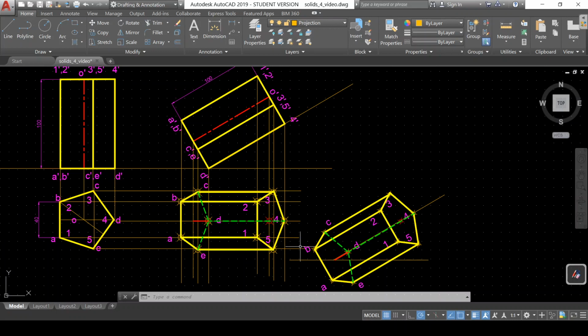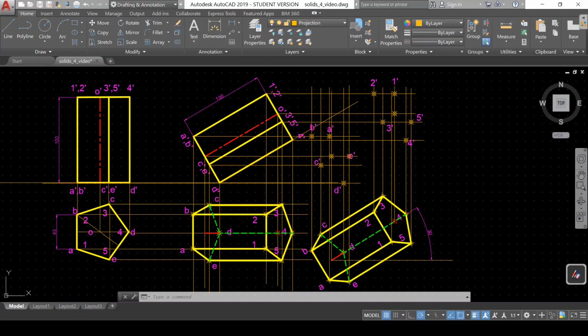In the second step, we have reoriented it. Now this axis view is making 30 degrees with XY or 30 degrees with VP. Now take the projections from this view, from the second step front view. The point of intersection should be named, and then we will connect those points. Now we have got these points by taking the projectors, and we have named those points. And now let us see how to connect the points.